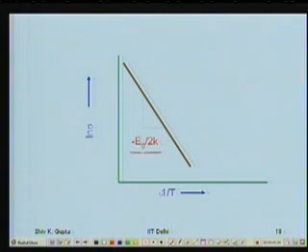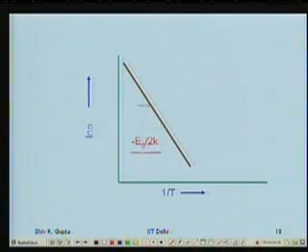And this information is what you can exploit if you want to use a semiconductor as a thermometer to measure the temperature. With the workouts, we get the conductivity at one temperature, we get it at another temperature like this, and from which it can be calibrated to temperature. Because this is reciprocal temperature, if you want it directly in terms of temperature, you can do that. So that's how you can exploit this, and some thermometers are made of semiconducting materials.